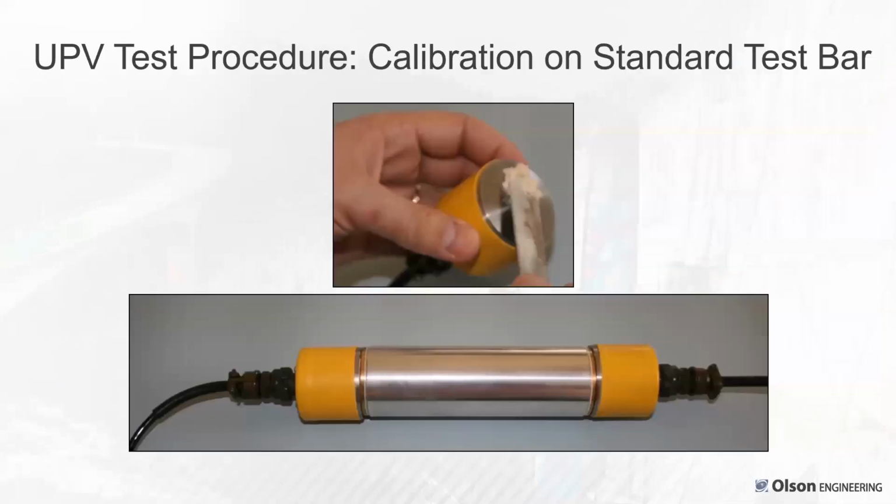So with the small ultrasonic transducers, you grease couple them lightly and put them on a calibration bar, which has a known travel time. You calibrate your system per the ASTM standard for testing, say, cores in the laboratory, and then crushing them to get a precise measurement, to 1/10 of a millionth of a second, of the time required on your testing.